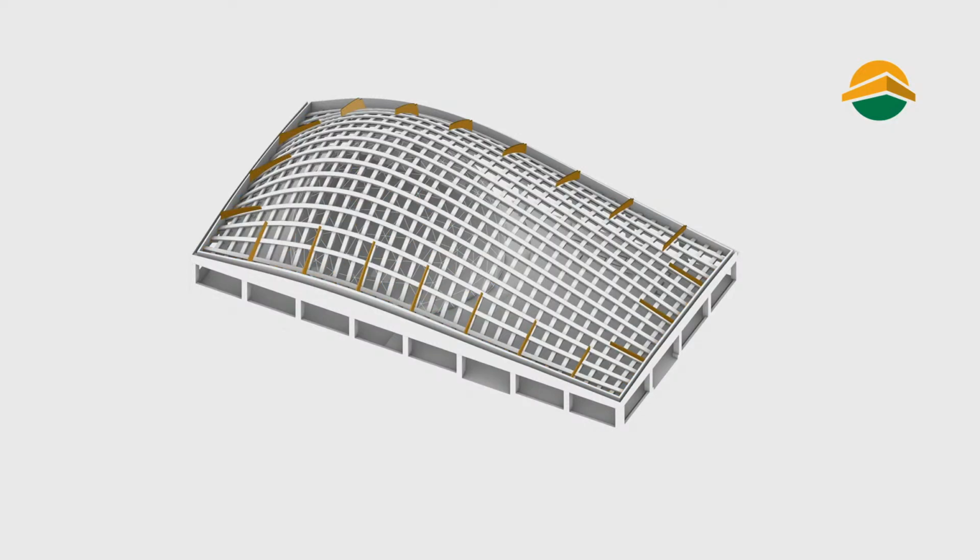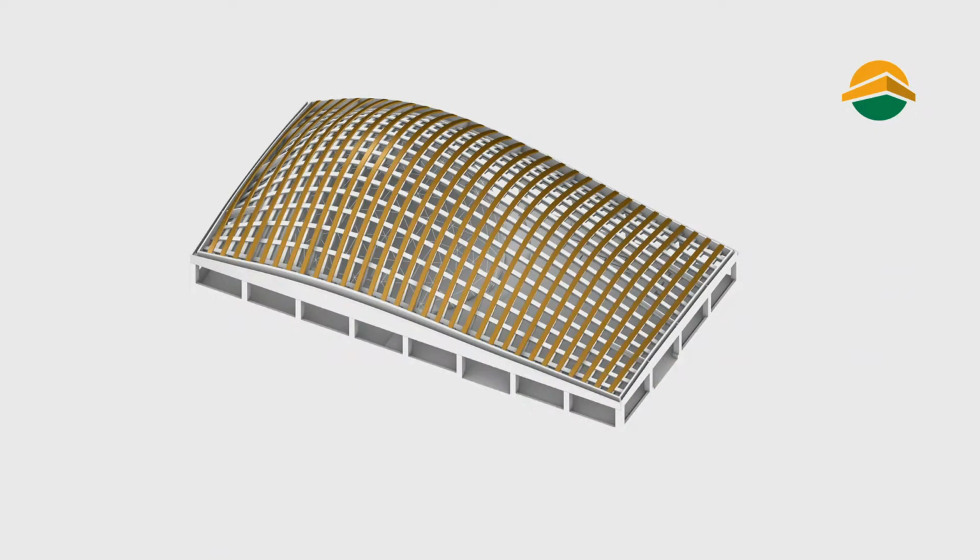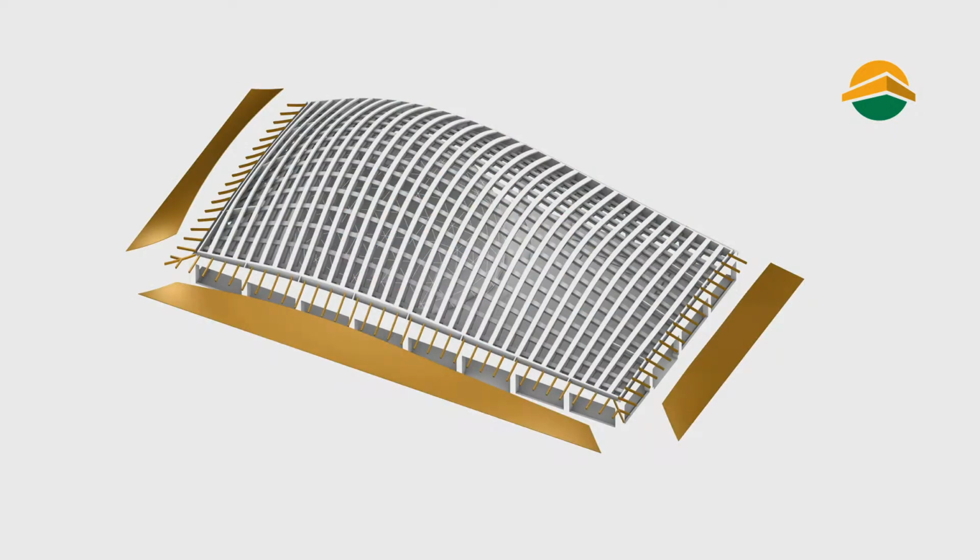Then we have some shear panels. It's a kind of stiffener where the grid shell meets the columns. And at the end, the last layer of lamellas, again bundled 5 lamellas, which are brought on site and then bent over the connectors. In the end, we have cantilever beams. Each beam also has an individual geometry due to the curvature of the roof and the cantilever panels.